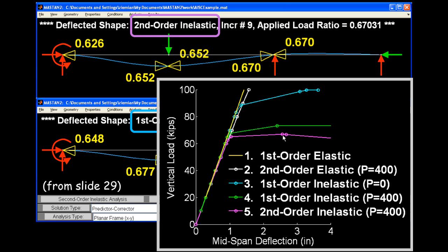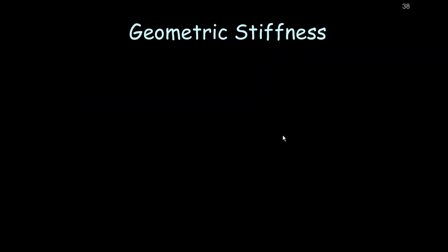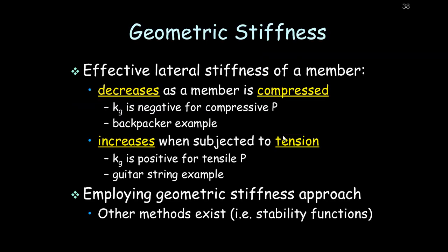Looking at slide 38, the question is this. Based on slide 38, is this why in X-brace systems we can use a tension member to brace a compression member out of plane? Yep, this is the exact reason for that. Perfect question. And then, adding on to that, how much tension is needed to significantly enhance that stiffness from the tension?